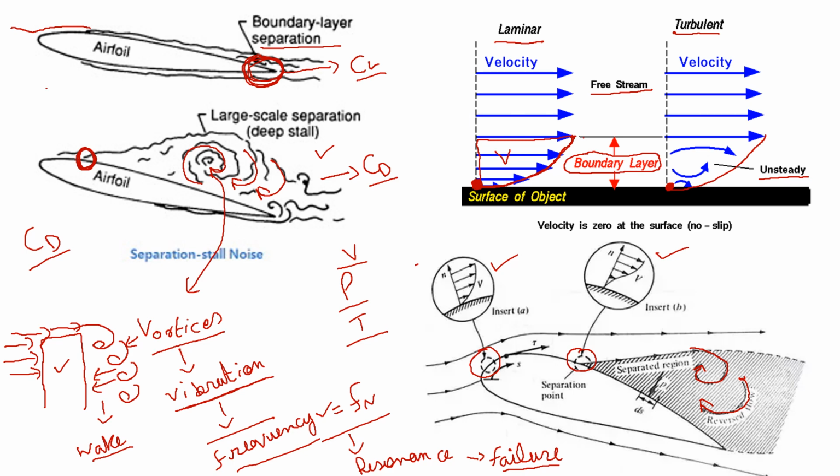So this is a very important form of analysis in which we study the flow separation from a solid object to see how these vortices are formed and what effect these vortices will have on the object under consideration. Again, in an aerofoil, they will result in a reduced lift coefficient and an increased drag coefficient.